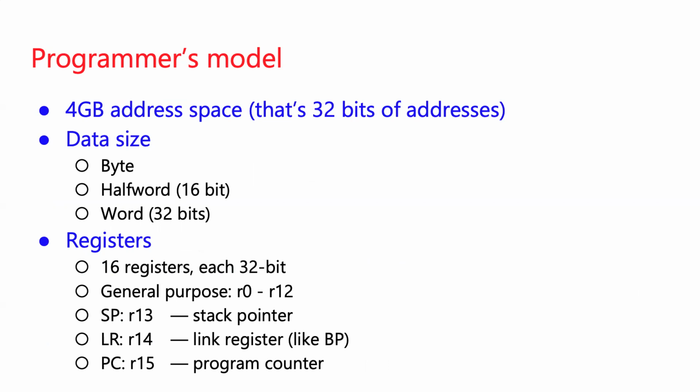So before we used byte-sized and what we called word-sized operands. ARM, at least the one we're looking at, has 3 sizes for operands: byte and word, but here word is 32 bits, so it's twice as big. It's a 4-byte quantity. And in the middle, we've got half word. So a 16-bit quantity would be called a half word, same size as what we would have called a word on 8086. We'll just call it a half word because word is going to refer to a 4-byte quantity instead of just a 2-byte quantity.